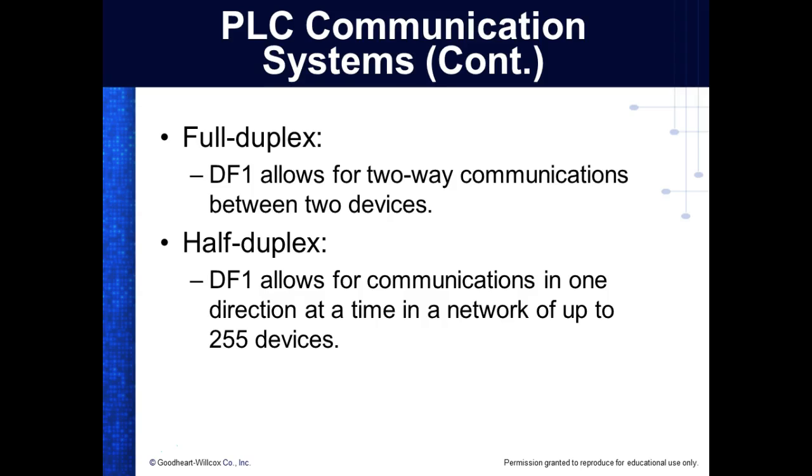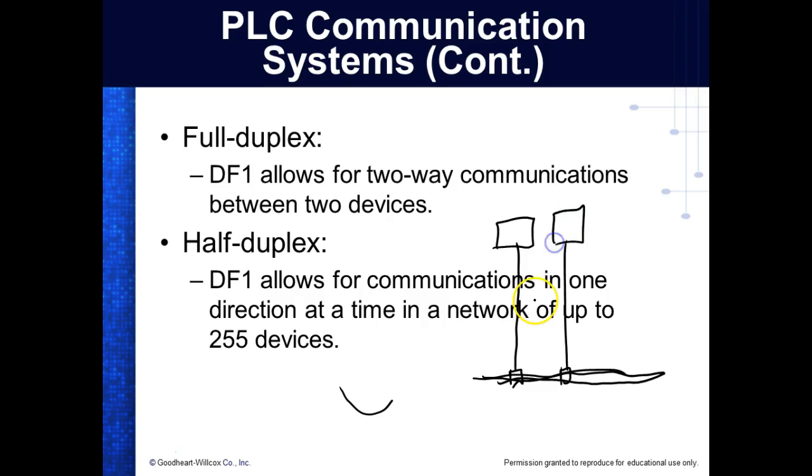Profibus is a bus topology. A topology is a term we use for networks, the way we connect networks together. So a bus topology would be, you come over here and you take a cable, and then we have 2. We have what we call a drop, where we have one main cable that runs the entire network. And then we come up and install these T's, and then this is where your PLCs or your nodes are.